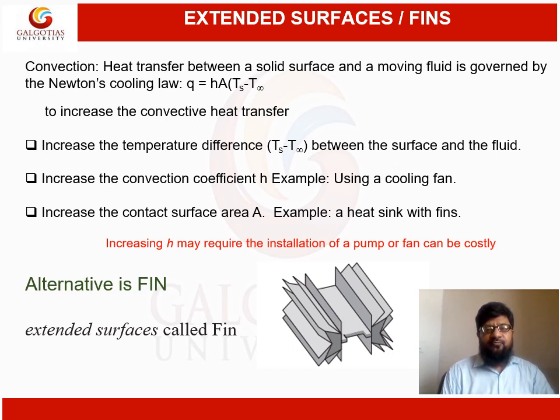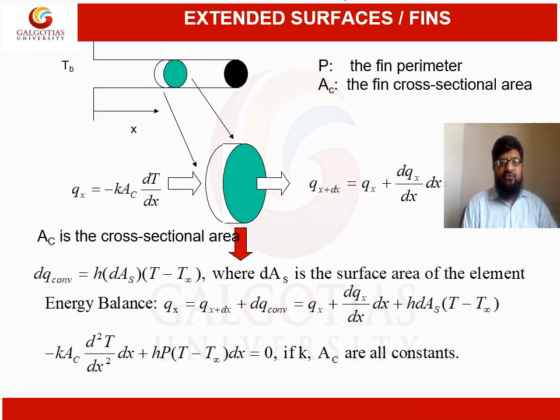So what we do is increase the heat transfer by attaching some extended surface to an object from which the heat removal is required, and thus exposing it to greater contact with the fluid. Such extended surfaces are called fins. So now let us perform an analysis of a fin based on the energy balance.